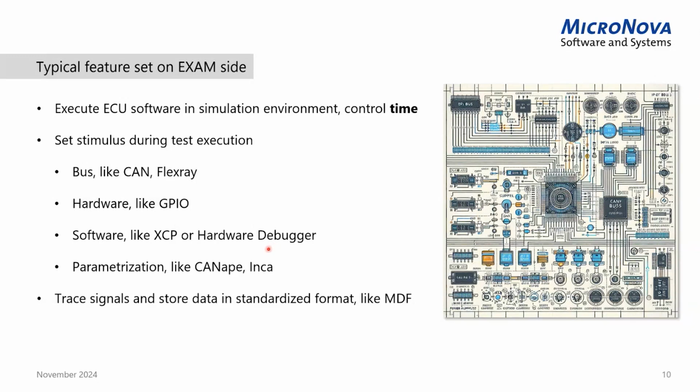Last point, we also, of course, like shown in the smaller example, want to do parameterization by using CANape or INCA tools, for example. And also here, we usually want to use what's available on the real test bench. We don't want to develop everything over and over again, but we want to reuse our existing tools. And the last point on the list is actually that we want to trace the signals and store them in a standardized format, like the MDF format, to be able to later evaluate our test cases that have been running inside our virtual ECU.